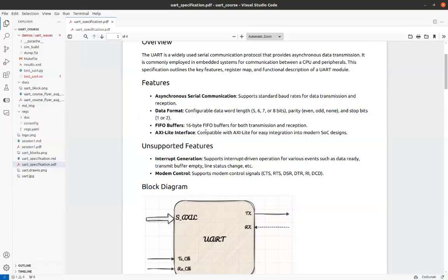And inside the transmitter and receiver module, we'll have some FIFOs to store 16 bytes of data, so that you can do more transmissions. Otherwise, unless you transmit one word, you cannot send again, unless it is finished. But since we're using FIFOs, you can keep on receiving.